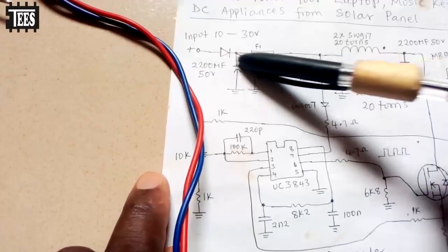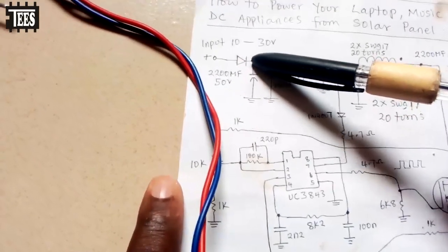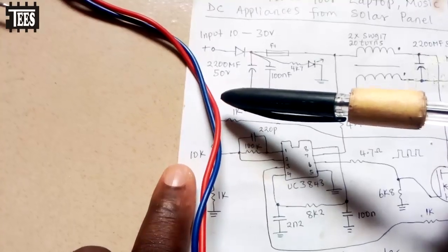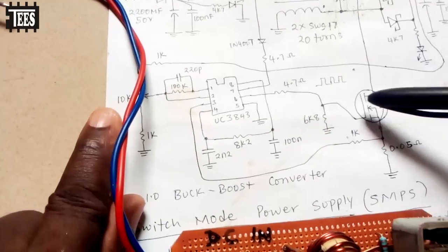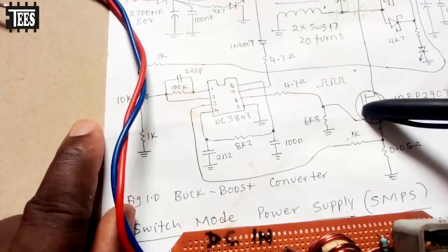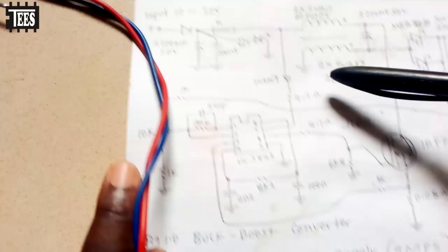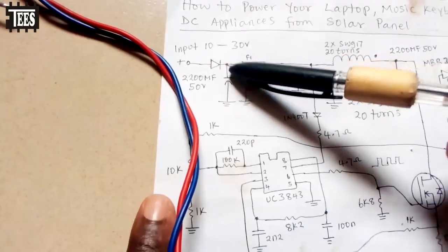Mistakenly, if you reverse this input, let's say you mistakenly connect this to a negative terminal and you connect to a power source, you connect the negative to a positive, current is going to flow and you're going to burn this, blow this transistor up. You understand? You're going to blow this transistor up.